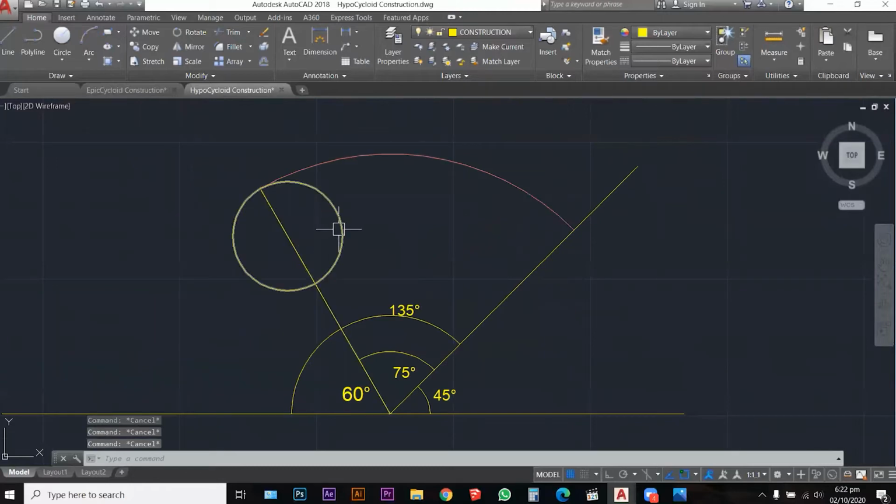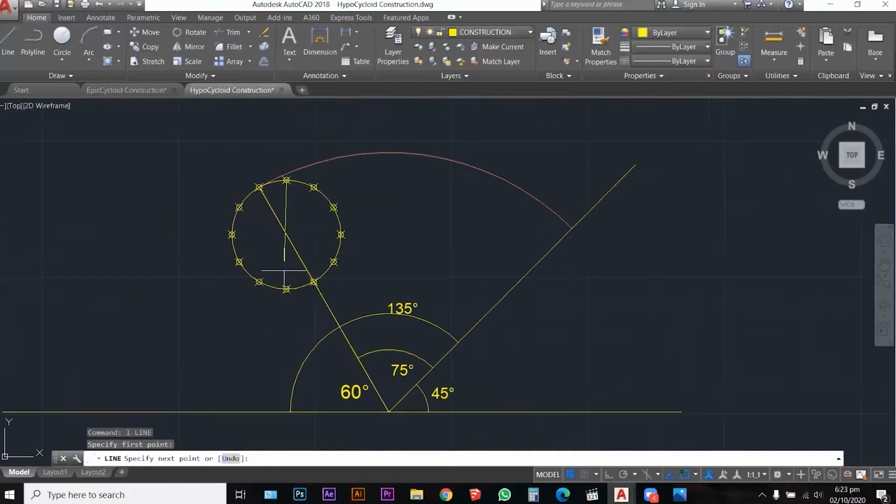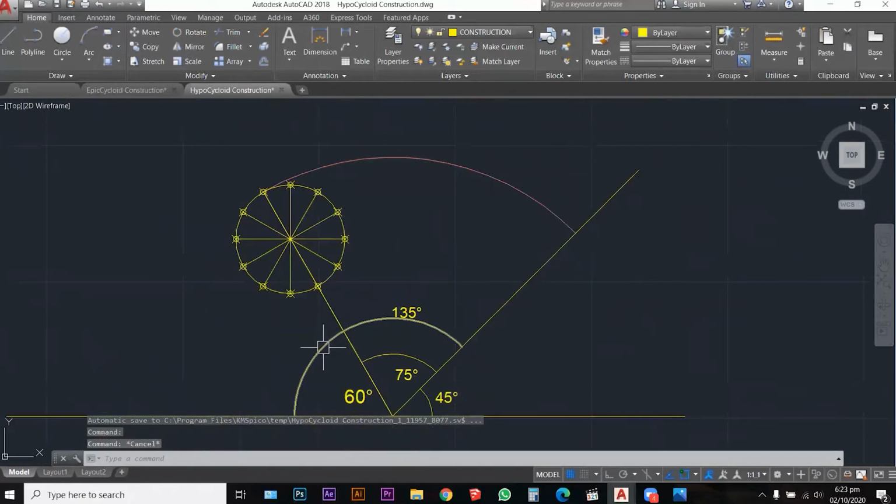All right, so let us go. First thing, we need to divide this circle into 12 pieces. So that's div. You select the circle, type div to get your divide command. Select your circle, type in 12, and it goes like that. The circle has 12 pieces, and they are all marked on the circle so that we can see where we click into. And it snaps into those points as I'm hovering over them. So at this stage, I'm just dividing the circle, not too hard.